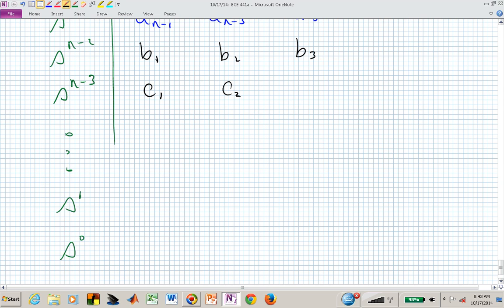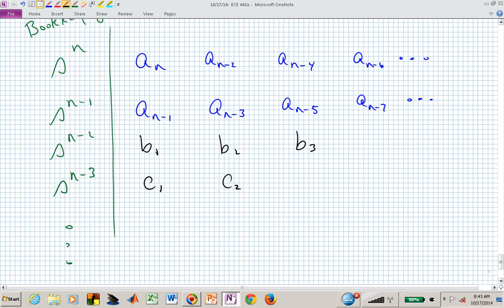So now let me tell you how you build or create that B sub 1 coefficient. It's similar to a determinant, but it's not quite the determinant, it's kind of backwards. To build the B row, we use the 2 rows above it. To build the C row, we use the 2 rows above it, the B and an A row.